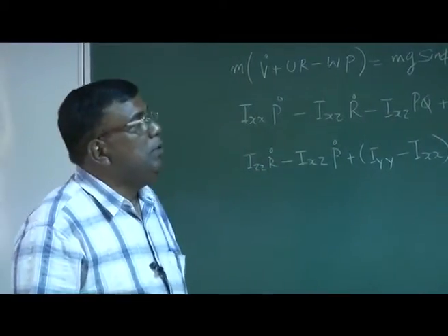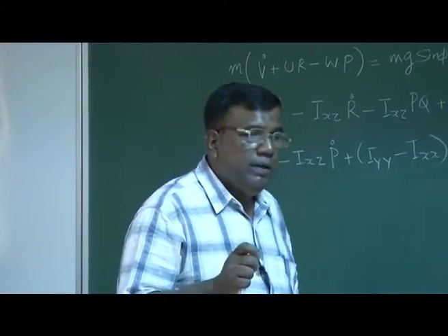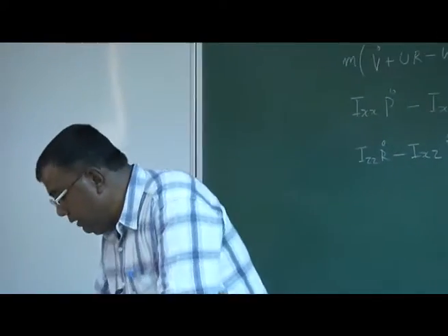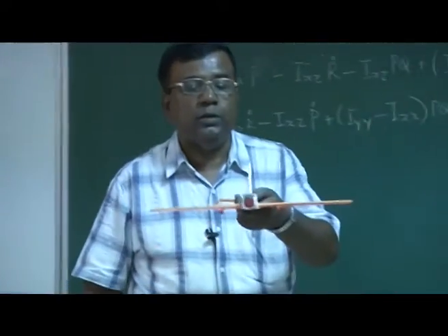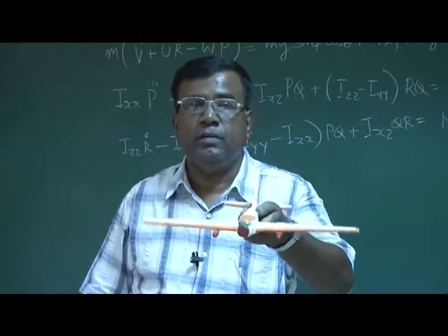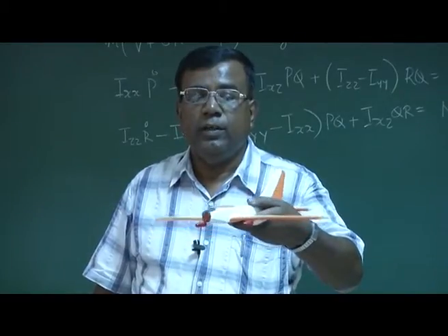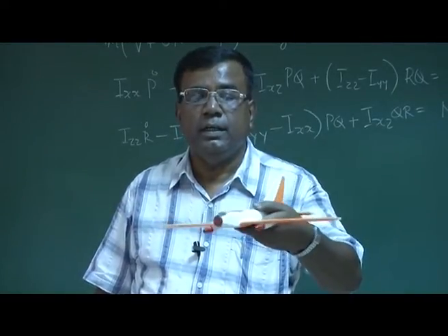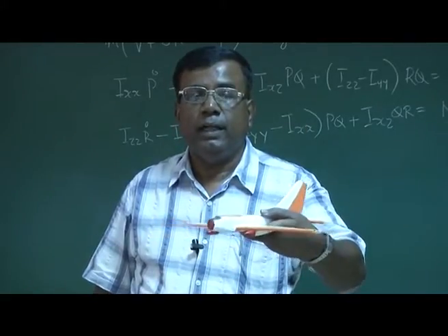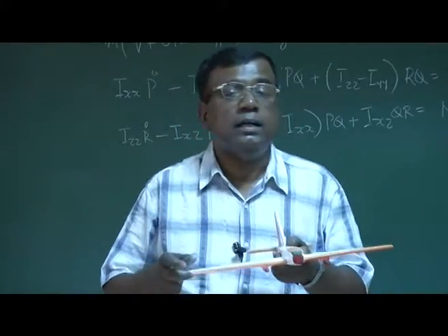Okay? We'll be doing a similar thing for the lateral directional case, but with a difference. First of all, let us understand that lateral motion means motion about the x-axis, and right wing going down is the positive bank. Directional is the right wing going back this way. So lateral is the right wing going down, and this is the right wing going like this when I'm flying in this direction. These two modes are generally coupled.